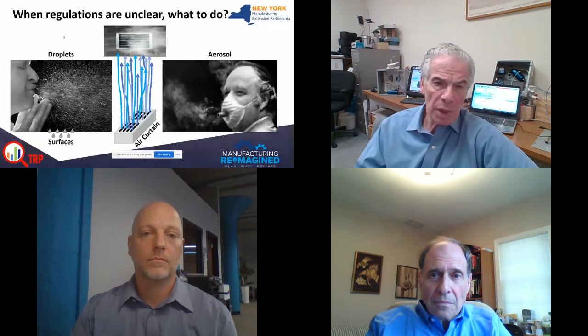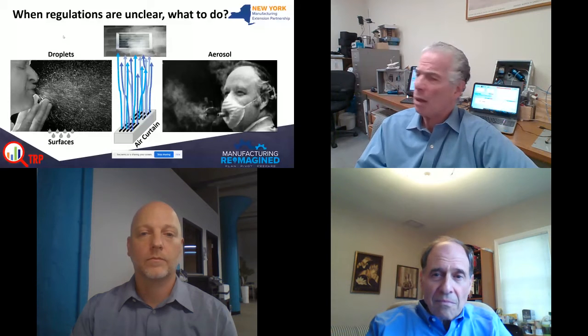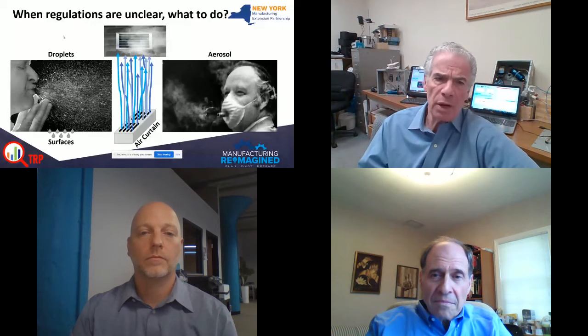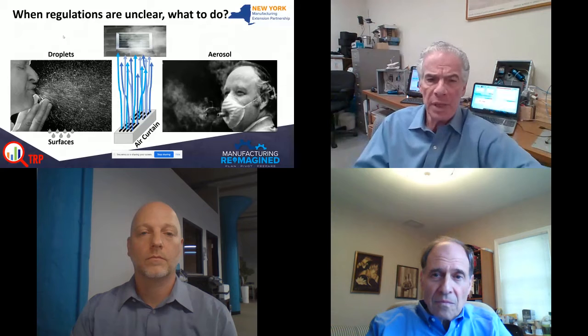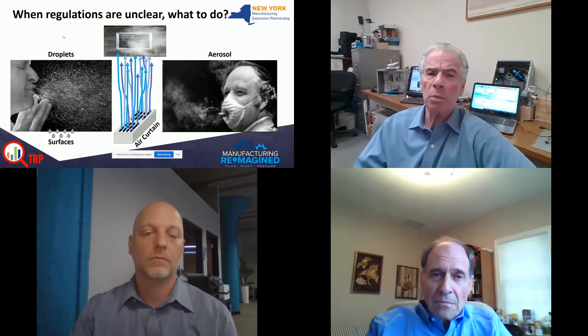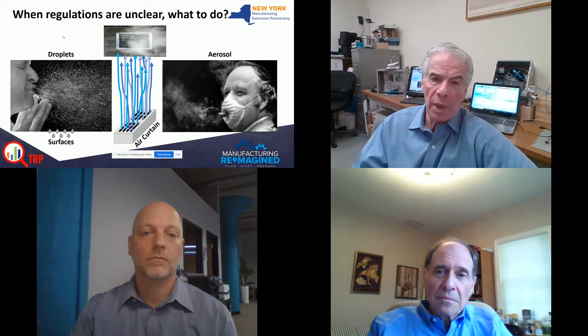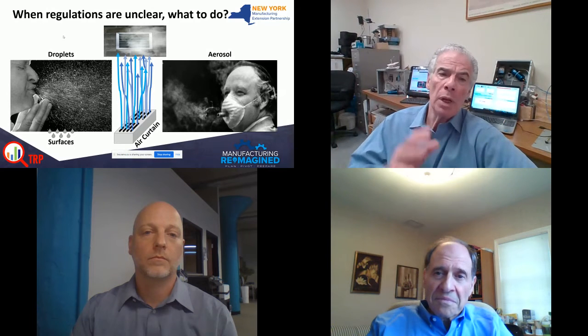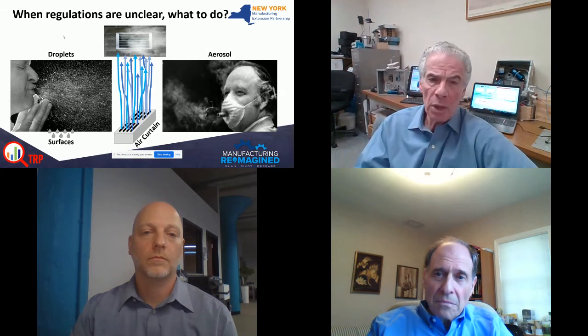One of the things we recommend and keep in mind is the value of having an air curtain. What do you mean by an air curtain? Nothing more complicated than a fan. If there are 2 people facing each other, and they do this frequently, having a fan which blows air away from them and hopefully toward an exhaust vent would be really very strategic. Don't sit near the exhaust.